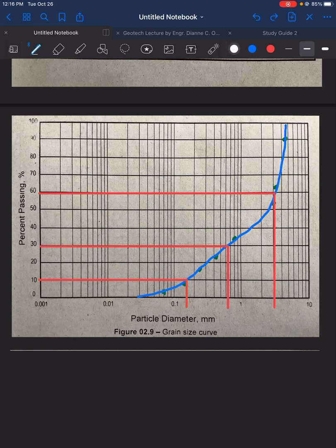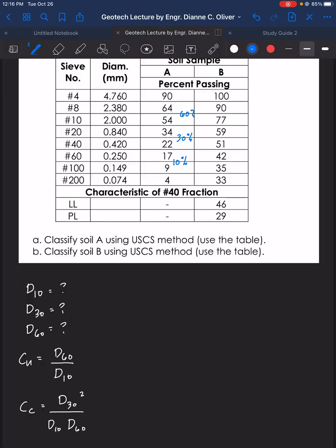The x and y is equidistant, meaning if we have here 1 unit, we have here 1 unit, another 1 unit, 1 unit, 1 unit. But if we are looking at a logarithmic graph, as you can see, the space is decreasing. Compare this portion here up to this portion. So we cannot just linearly interpolate to find the 60% diameter. Okay? So the first method is graph.